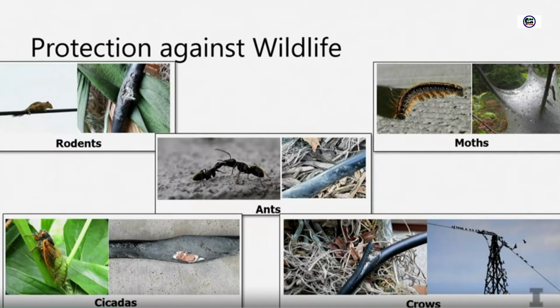On the other hand, you have things like moths and ants. These things burrow into cables, and they lay eggs and they build nests. The problem is insects are conductive. When they get inside cable, they can cause interference. They can cause short circuits where information can go between cables. A lot of times they move around, so they can create transient interference. This can be really hard to debug.